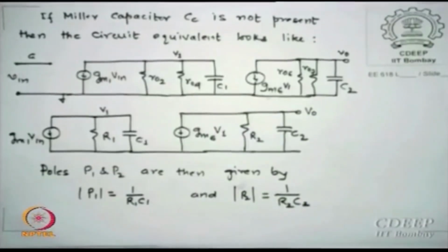Now if I have these new poles with CC removed, is that clear? No feedback, that is open loop system, AOL. Same equivalent circuit, the CC here has been taken away. Now, it becomes an interesting case to put CC. What is CC is also called Miller capacitor. Compensation is what it is doing, but it is essentially Miller capacitance. So the compensation is also called Miller compensation, because it is a Miller capacitance which is doing the job.